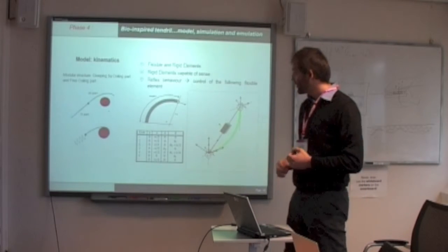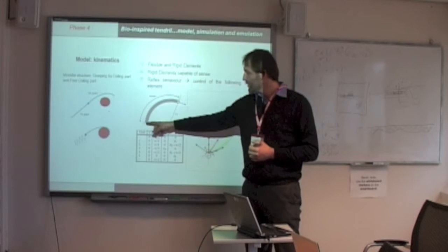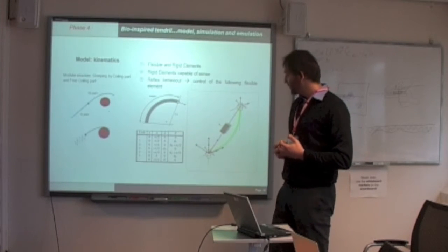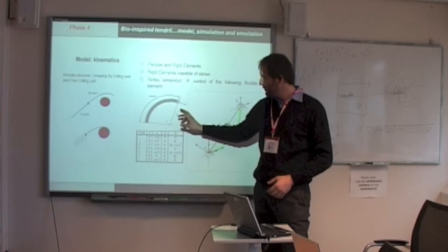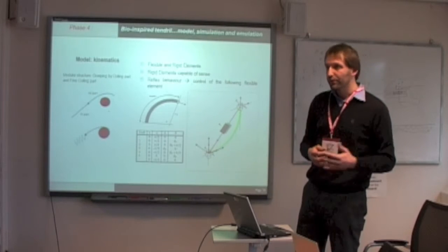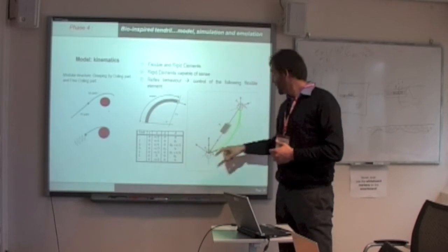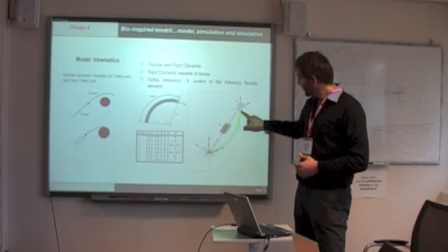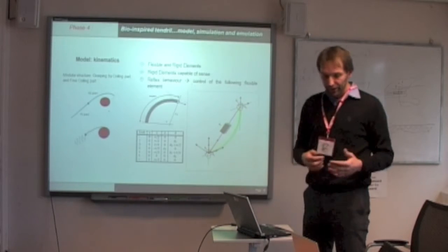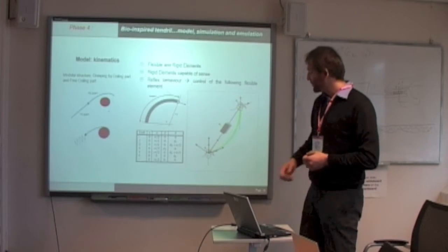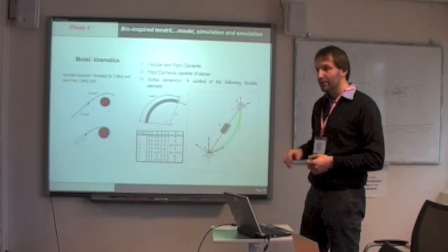So for each subsection we can define our kinematic model. Starting from the curvature, the length, and the angle of curvature of each small section, we can model with different joints and pairs from a robotic point of view, so universal or revolute joints and the prismatic joint.